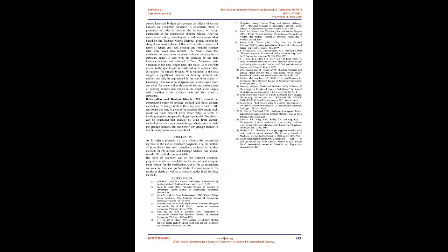In this study, the thermal behavior of curved steel box girder bridges is analyzed while taking the solar radiation effect into consideration. For the analysis, a method of predicting the three-dimensional temperature distribution of curved bridges is used. It uses a theoretical solar radiation energy equation together with a commercial FEM program. The behavior of the curved steel box girder bridges is examined using the developed method, while taking into consideration a diverse range of bridge azimuth angles and radii. This study also provided reference data for the thermal design of curved steel box girder bridges under solar radiation, which can be used to develop design guidelines.